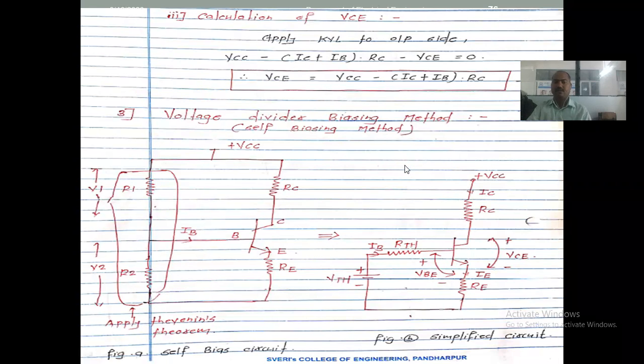Now, as we have completed the revision part, we move to the topic of voltage divider biasing. In all applications where we use a transistor, this is the most used method for biasing your transistor. The reason is that it gives a more stable output, and it doesn't have the disadvantages of other configurations. This is why voltage divider biasing is used more.